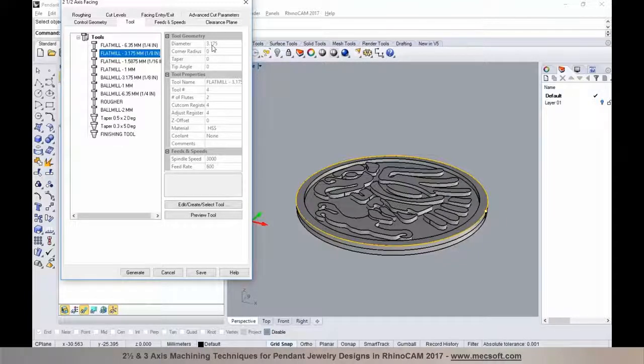You notice that the tools I've defined here are loaded from a library, in millimeter units, since the part is in millimeter units. So you need to have a library of tools for inch units and millimeter units, and these libraries will be loaded based on the library you select to load. The first time you load a library, our CAM module will automatically load the last loaded tool library for you. So it saves you time from having to go back and locate the tool library to load it again.